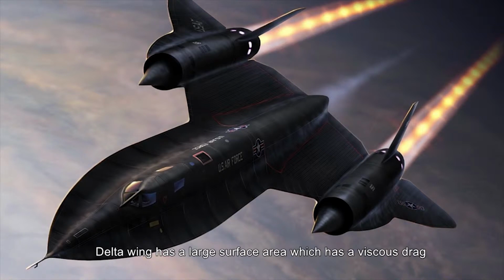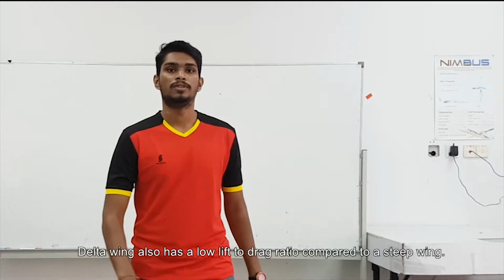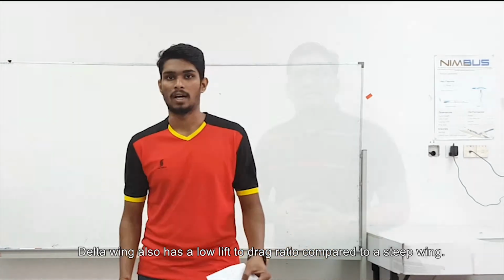The delta wing has a large surface area which has viscous drag for the same amount of lift, which is the same amount compared to the high aspect ratio wings. And the delta wing also has a low lift-drag ratio compared to a swept wing.